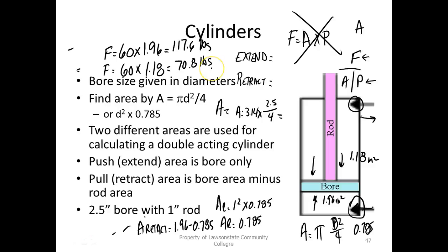You go out there and do all your calculations. You want to lift a 500-pound load, and you do all your calculations for 500 pounds. And you go out there and it won't lift it because you didn't take into consideration the efficiency of your system. That's something they're starting to provide even on electrical motors. For years, they would give you this information, but they wouldn't give you the efficiency of the motor. That's required now on the nameplate of a motor.